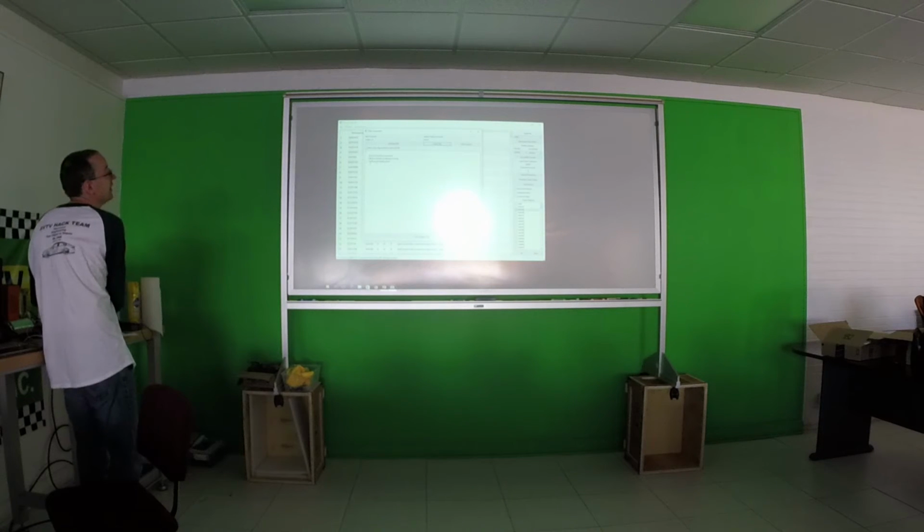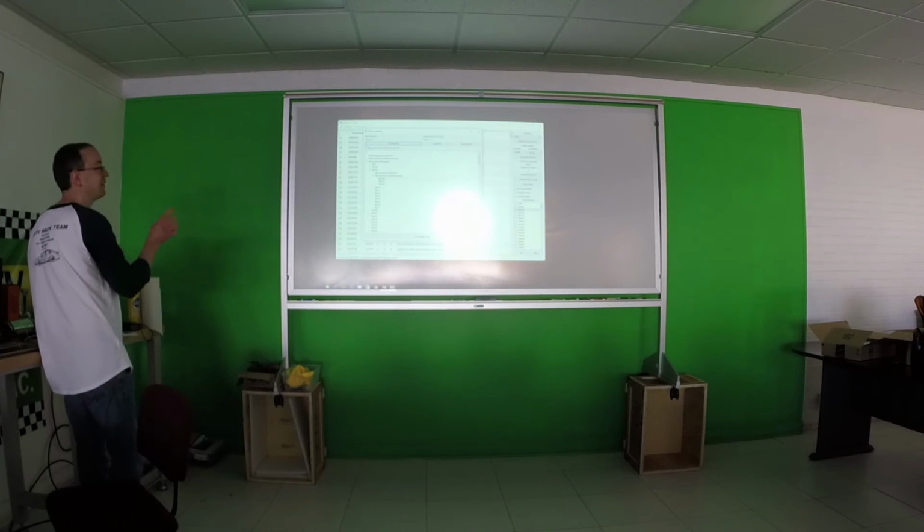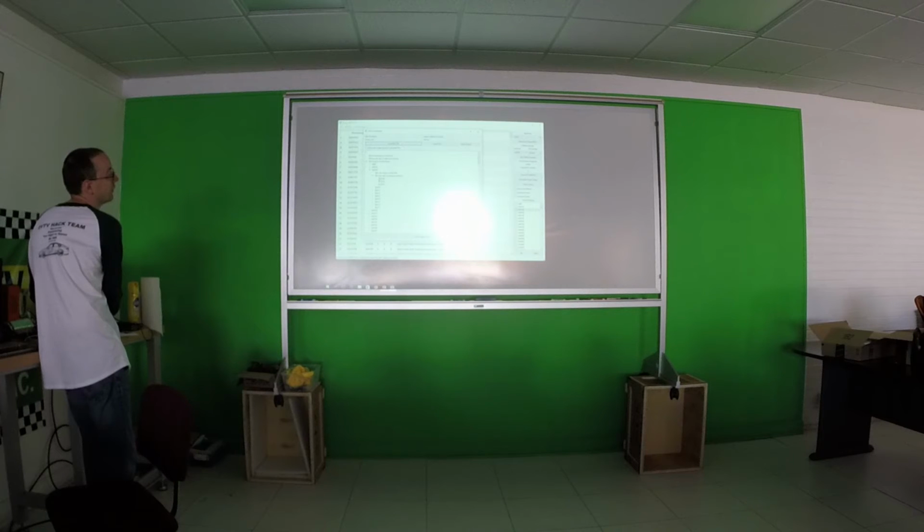What you'll see here is if an ID was only found in your file of interest, it'll be listed. If an ID was only found in your reference frames, it'll be listed. Otherwise, these are all the IDs that were the same between the two. In 106, the reference frames have some bits set, and here's the actual bit number. When I showed that 64-bit grid, these are the numbers from the grid: 46, 47, 55. But this is the byte and the bit within that byte. So byte 5, bit 6, and byte 5, bit 7 were only ever set in the reference frame. They weren't set in the cruise frame. Does that mean something? Probably not.